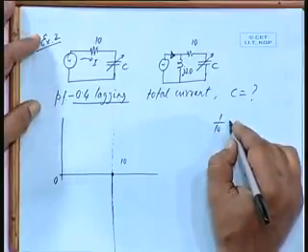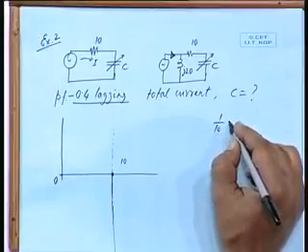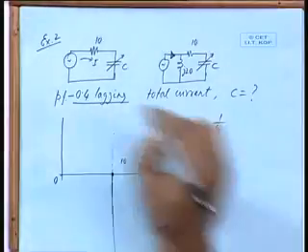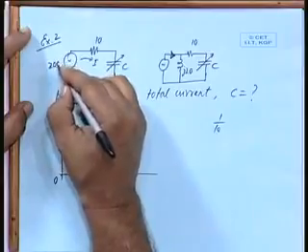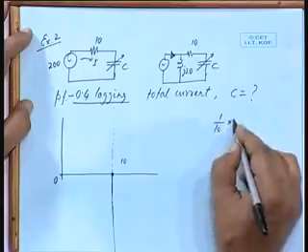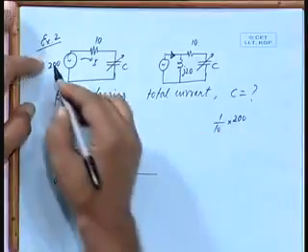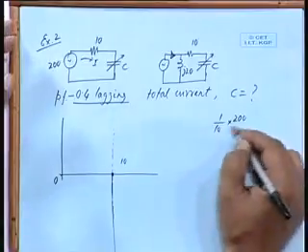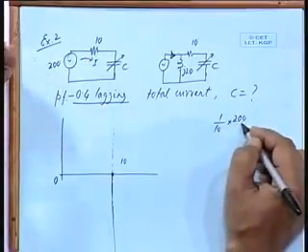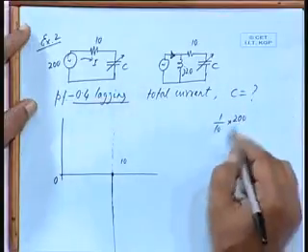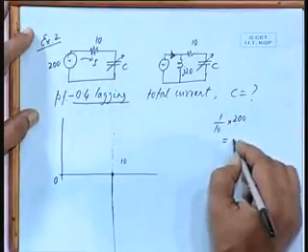I can choose any scaling factor, all right. Let us choose a scale factor of 200. This voltage is 200, or straight away we can multiply by 200, because after all it is a voltage multiplied by the admittance which gives me the current. So, if I take straight away a scaling factor equal to this voltage, then that represents the current. So, 200 into 1 by 10, that gives me 20.